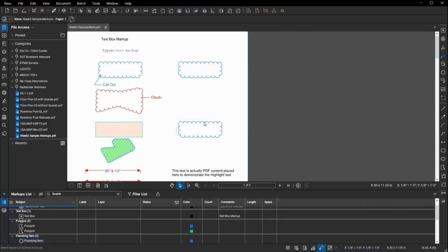You can also take advantage of markups that are already in the drawing by turning on your snap lock to markups. It's down in the status bar. It's right next to reuse, and it says snap to markups the same way it says snap to content. So if I say snap to markups, now when I go in here and start to place a polyline, you'll notice all of these projected intersection lines that are popping up, giving me the opportunity to enter a data point that will start my new markup at exactly where these things would have, like the center of this and the edge of that and so on and so forth.